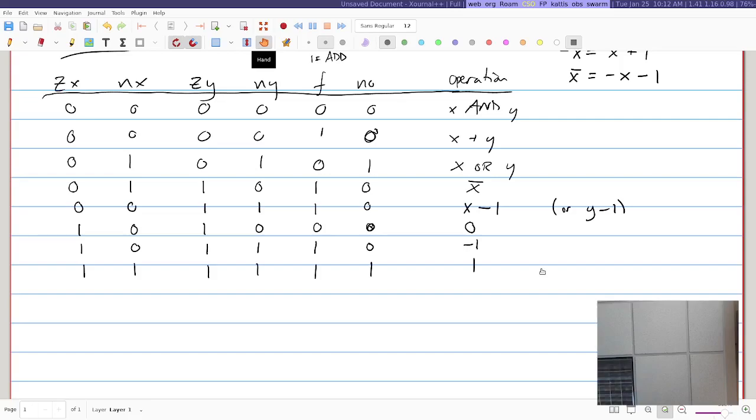You could imagine that your ALU has a big list of operations it can do, and some kind of codes that code for each one. Basically you'd have a whole bunch of muxes that say, I'm going to do all these operations, and then based on what bits you gave me for your code, I'm going to see, okay, is it this one, is it this one, is it this one? I'm going to choose the right output.